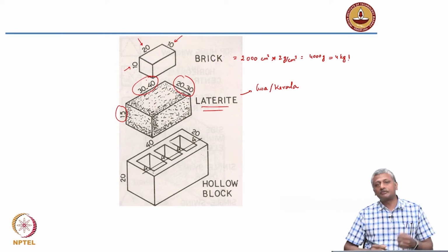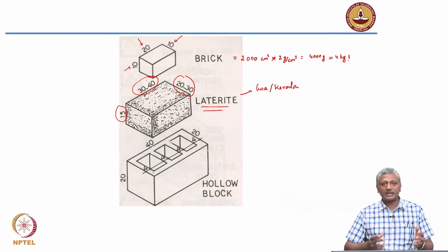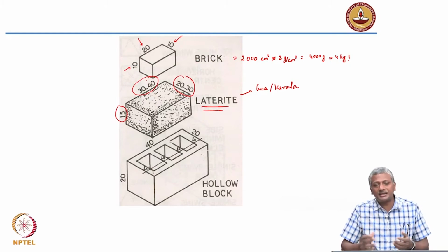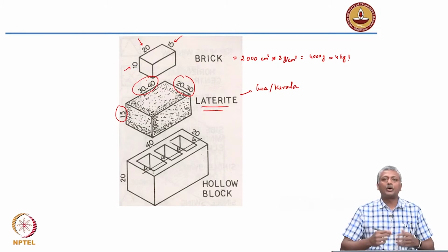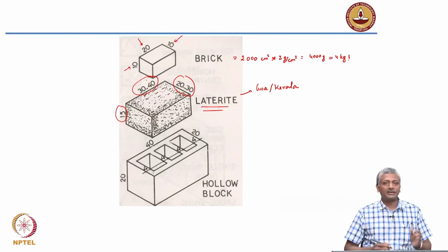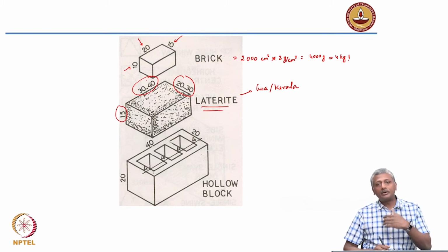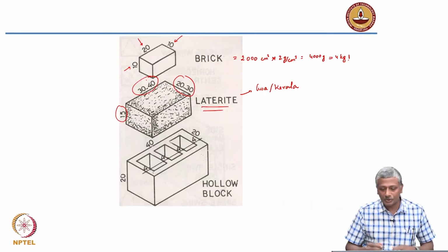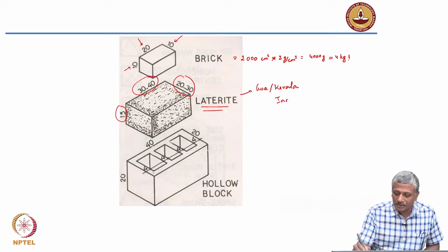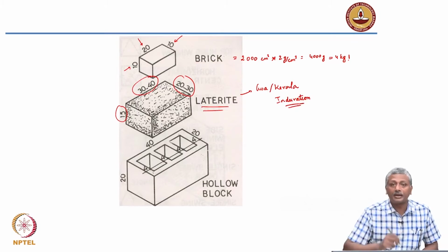It's a very different type of stone, okay, as compared to granite or limestone or quartzite, which are extracted from quarries, and those typically don't change their structure very much in the long term, except when they are getting weathered, and that's when adverse reactions actually happen. With laterite, on exposure to a benign atmosphere, they will slowly gain strength and indurate. The process is called induration. The slow strength gain with age of laterite blocks is known as induration.